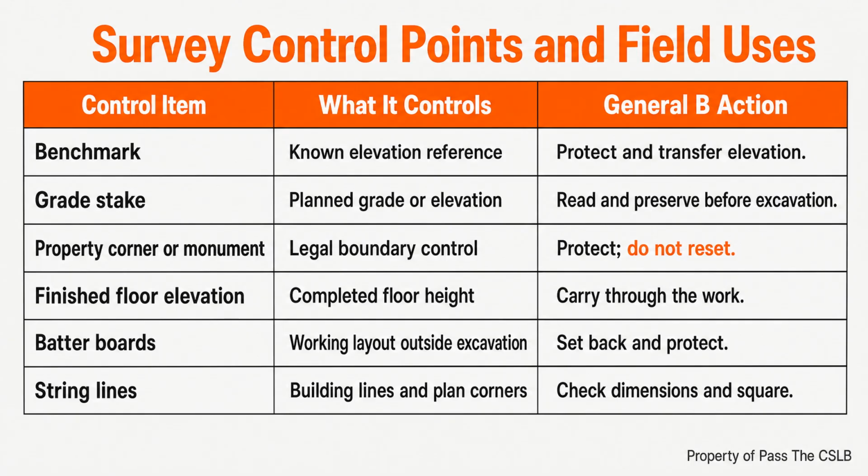The same control mindset applies below ground. Before excavation, the proposed area has to be made visible for the underground service alert process. California requires the planned excavation area to be pre-marked in white. White paint, white stakes, white flags, white chalk, or baking flour can identify the intended dig area. The color matters because the white marks communicate the contractor's proposed excavation. The utility owner or locator then uses the established utility colors for the facilities. Mixing those roles creates confusion before the first bucket enters the soil.